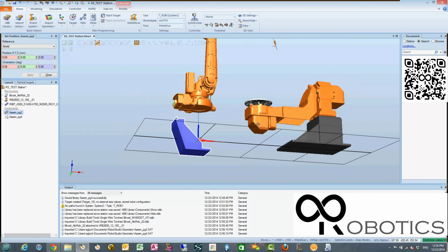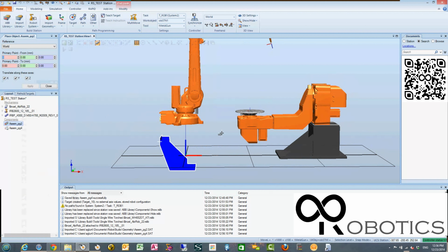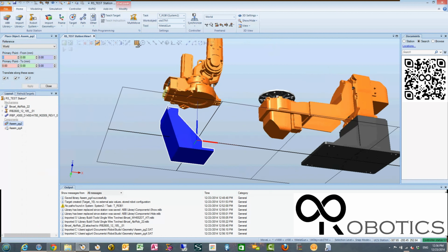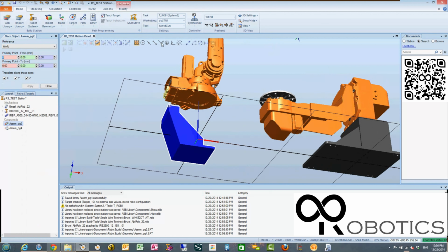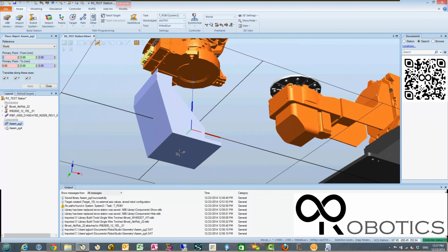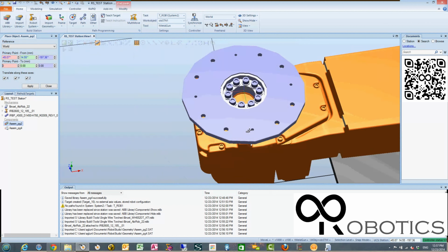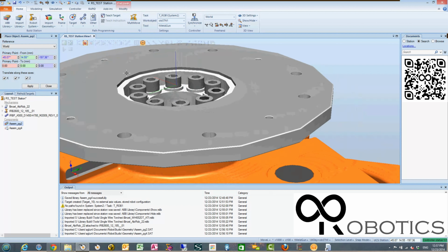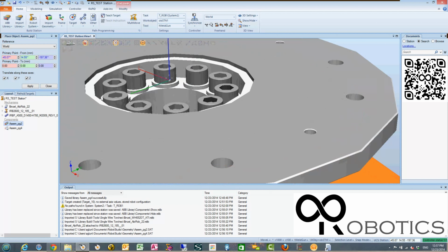by using a place one point. So I usually try to get them the right orientation, and then I'll place one point, and depending upon what we have selected up here will change where you're selecting. So here I'm going to select this snap object. It's the one I normally use, and I'm going to select the middle of this face here, and go to the middle of this face here. Sometimes it's kind of hard to select this, depending upon the selection tools. I'm going to try surface, and then go to middle, see if it'll select where I want, and then change this to frame, and there we go.